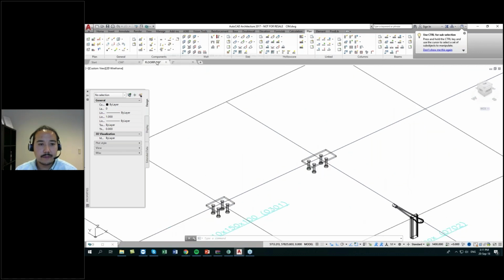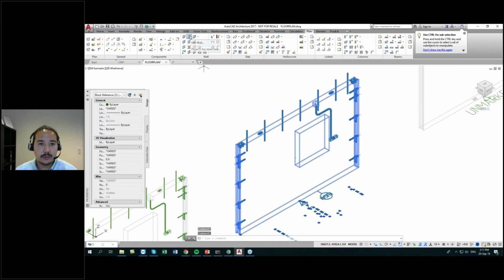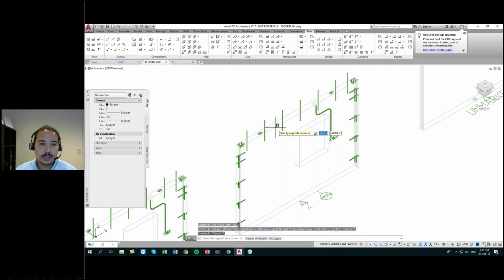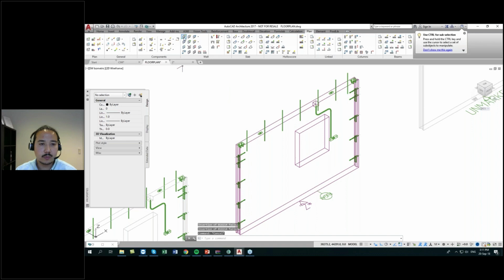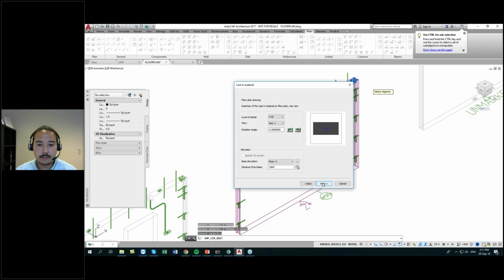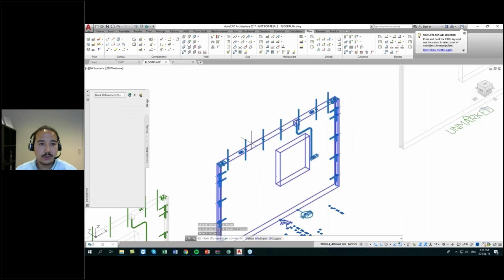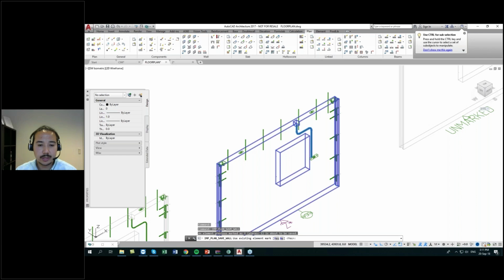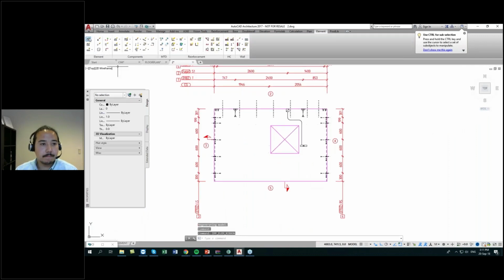So when I go in here to my floor plan, of course I want to change my plates here. I can either do that by editing it and removing it, but what I can also do is go in here and say regroup wall. Then it unlocks the wall, it's not one block anymore. I can go in and say edit custom material and select my 2 plates. And instead of this one here, it should be this one. Like this. It will be a bit out of the element, that's okay. And when I save my element now, it will get regrouped again, and I cannot select them anymore. And of course go in here and update the element.